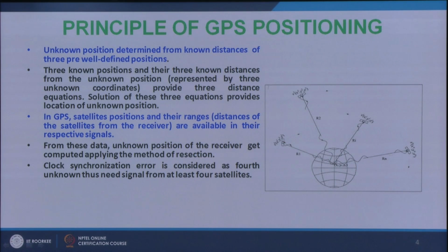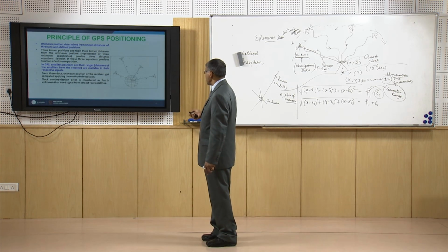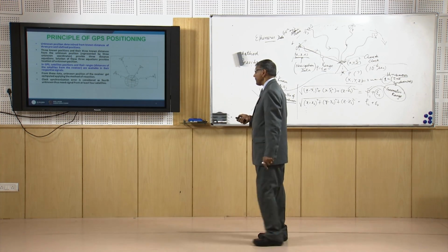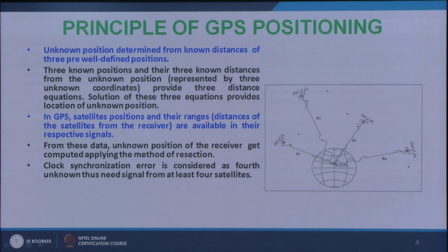This is computed from the GPS code information as well as phase information, and if the time can be calculated, then the velocity of propagation of an electromagnetic signal is the velocity of light. So from that we can get these ranges, and if we know the ranges then that distance equation can be solved, and by solving this equation we can get the location of the receiver.